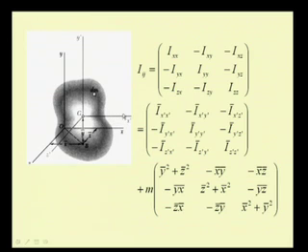So, now when we write all these individual quantities in terms of their centroidal axis and the location of the centroid, that is x bar, y bar, z bar in this coordinate frame O, x, y, z, we have this as the inertia tensor in the centroidal frame of reference plus m times y bar square plus z bar square, minus x bar y bar, minus x bar z bar, etc. We already know that these are the coordinates that we have obtained from the parallel axis theorem.